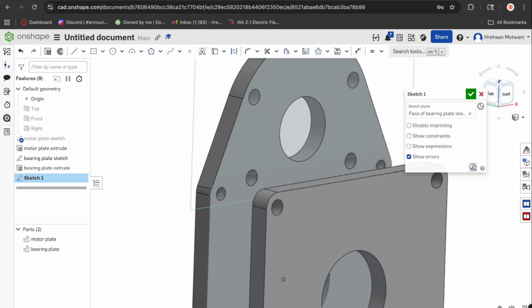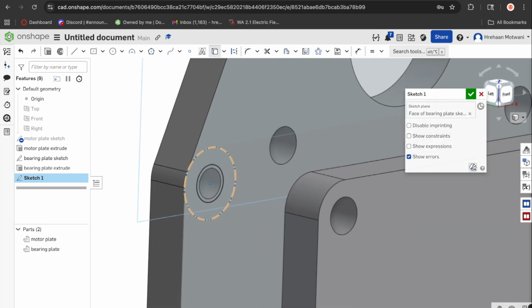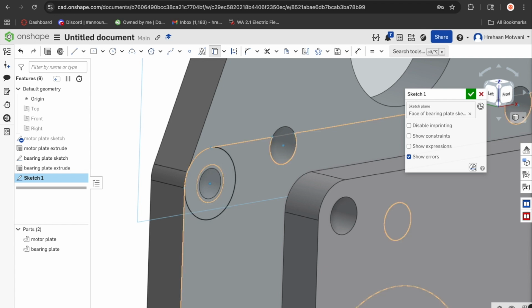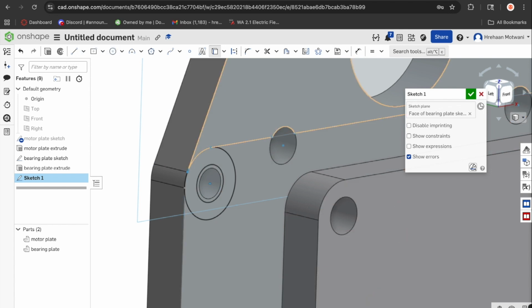And then we can use the use tool again to just bring these to here. Make sure you don't click on the hole from the first plate and you click on the sketched hole, because this hole is a different size. So then your spacer sketch is done, and you can name this.